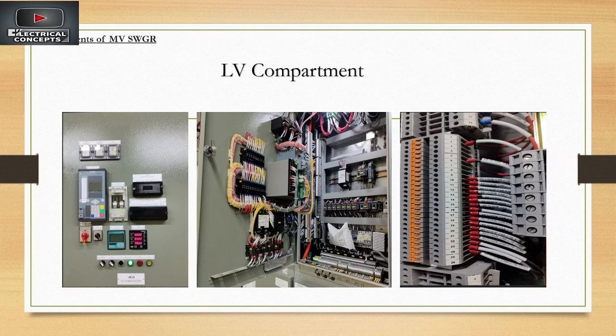Bay control will give a choice to connect with the substation automation system. Basically, this is the bay control and protection unit, BCPU. This can be from ABB or Siemens, and these are IEC 61850 compliant devices which can handle both control and protection functionalities.